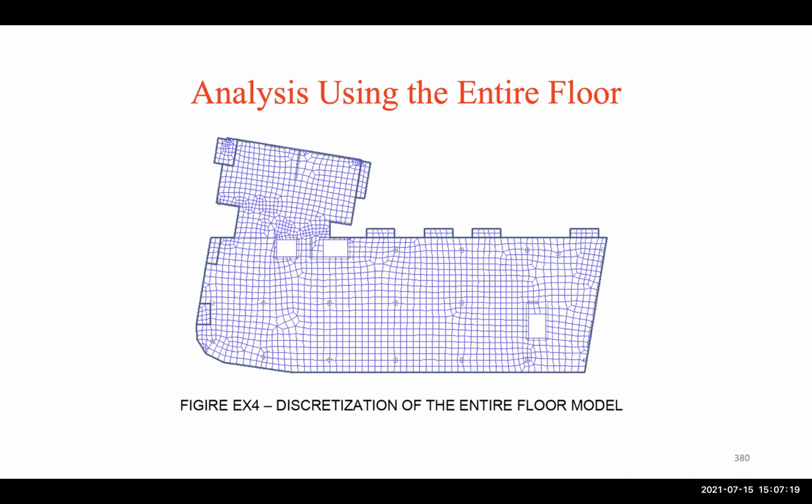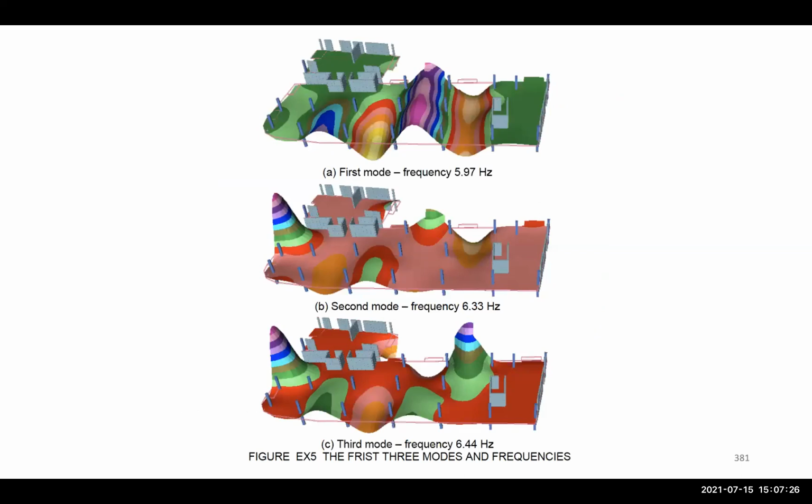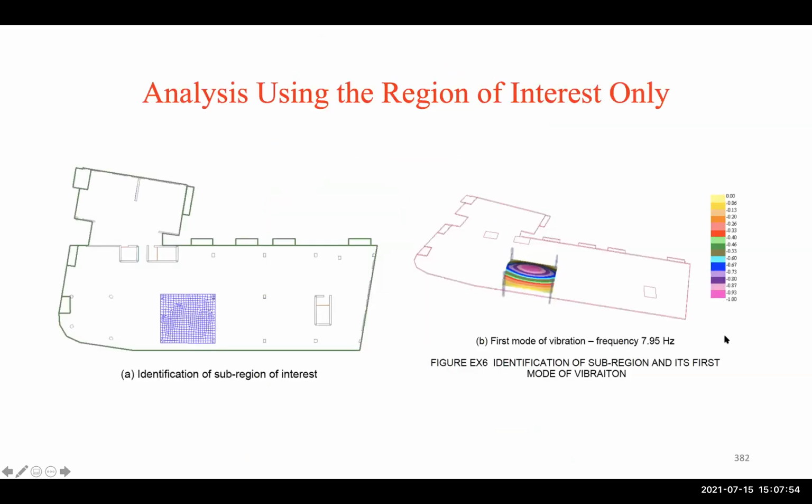Okay. Good. So using finite element analysis of course for the floor, if you run vibration analysis, you can see that. I mean, you cannot get better than this, basically. So you analyze the entire floor, not only one panel, because it has continuity from this side, continuity from this side. The edge panel, for example, this one here, does not have continuity from this side. So you can see the first mode vibration, second mode vibration, third mode vibration, etc. Okay.